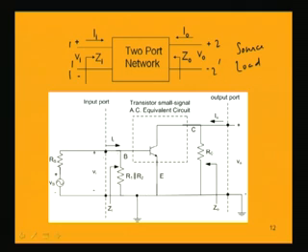So, in this two-port system there are quantities: input voltage, input current, output voltage, output current, and conventionally the polarities and directions are shown like this, that is, the upper point is positive with respect to the lower point for these voltages, and the currents are towards the system. I1 and I2 are conventionally shown towards the two-port system. So, Vi and Ii are the voltage and current at the input port, and V0 and I0 are the voltage and current at the output port.